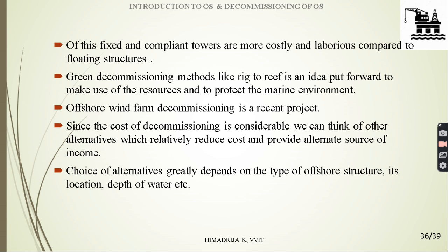As I mentioned about the three types, fixed and compliant are more costly than floating structures. And rigs to reefs is now a green decommissioning method, or an alternative to decommissioning, which is now being adopted on a larger basis. Also, the offshore wind farm is a recent project which is coming as an alternative to this decommissioning method. So the choice of alternatives depends upon the type of offshore structure, its location and the depth of water.